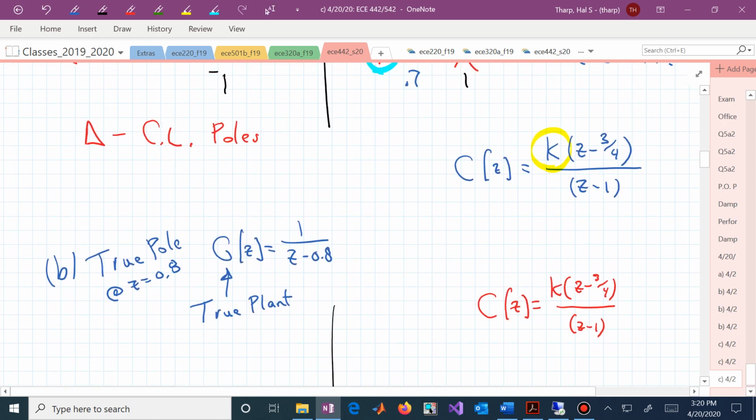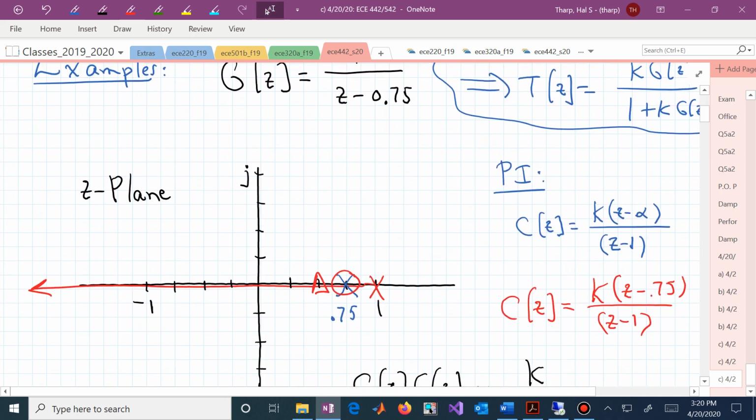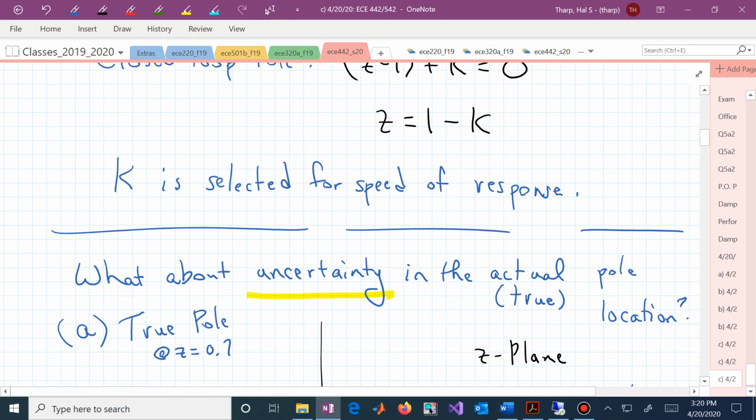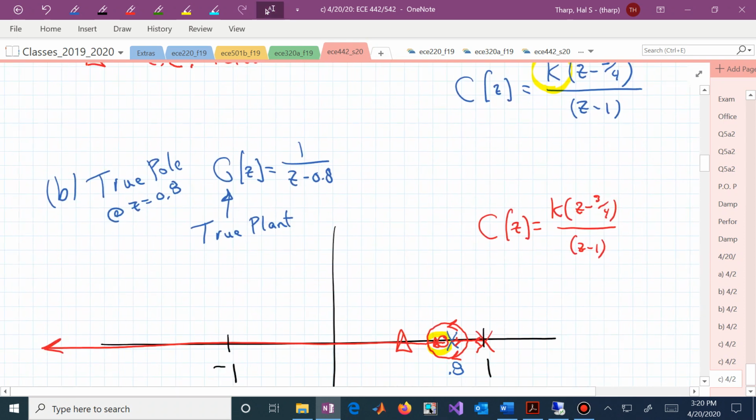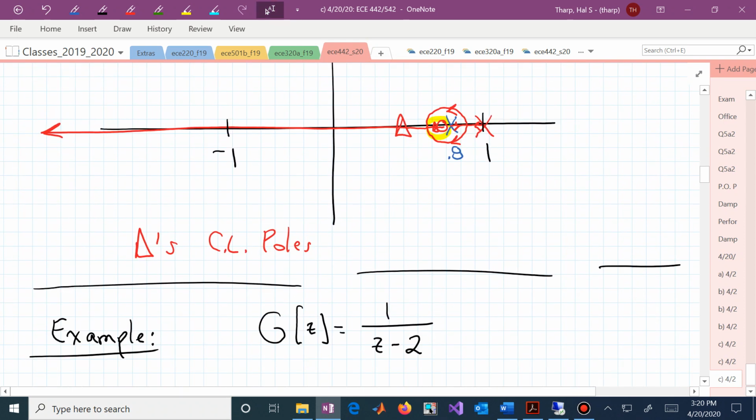We're still ending up with that triangle on the left in almost the same location as where we had it from our original design for that particular system. That's now one design, and we didn't even get all the way to PID. We went to PI, and that may give us acceptable behavior.